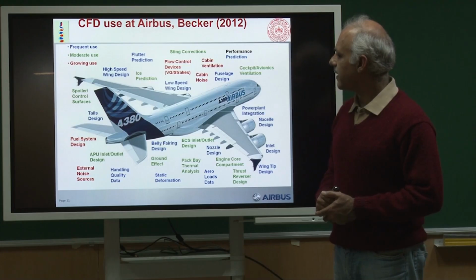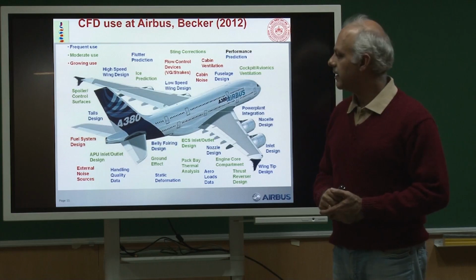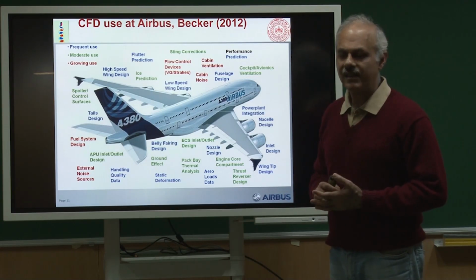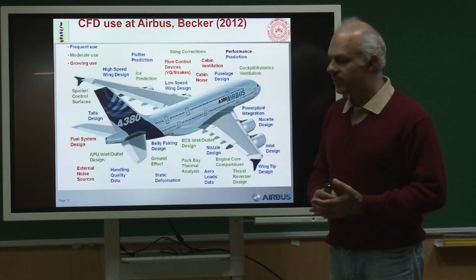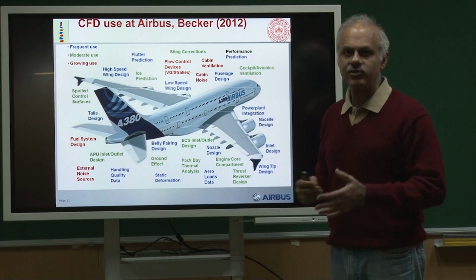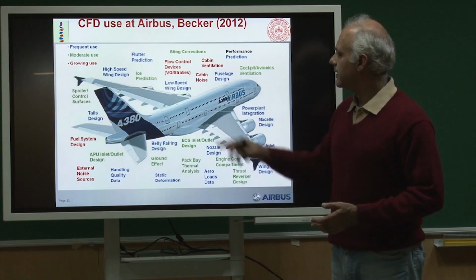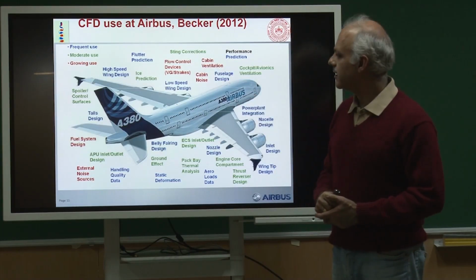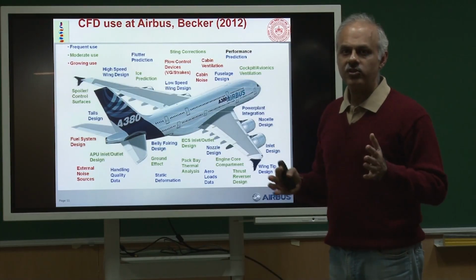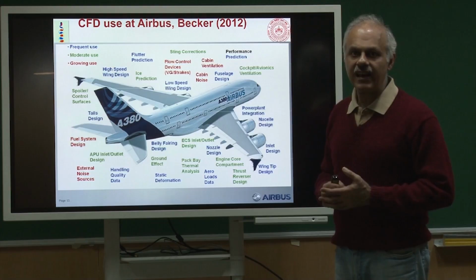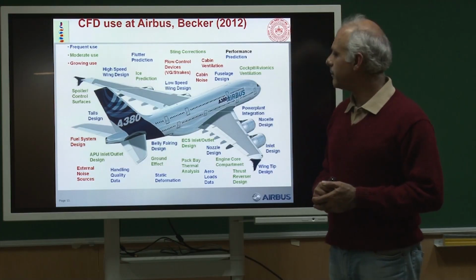A little less use is when you do wind tunnel experiments, for example, then you need to support your model, and that itself changes the flow. Unlike in CFD, which is kind of a standalone model where there is no interference, if I have to hold a model inside a wind tunnel, then I need to make some corrections. So one can use CFD to make those corrections. Wall effects: if I have a wind tunnel where my blockage effects are large, the walls are too close to the model, those corrections I can make using CFD.